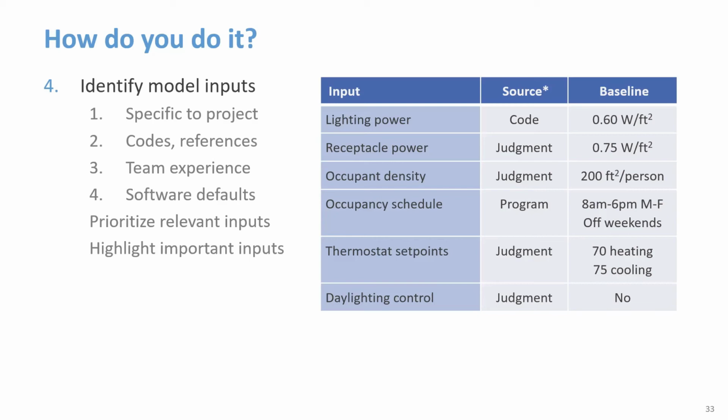So if, for example, the goal is an accurate energy end use intensity estimate, then it'll be important to gather information about likely operating schedules and plug loads and any likely unusual energy end uses, because of course they have a significant impact on the total energy consumption.